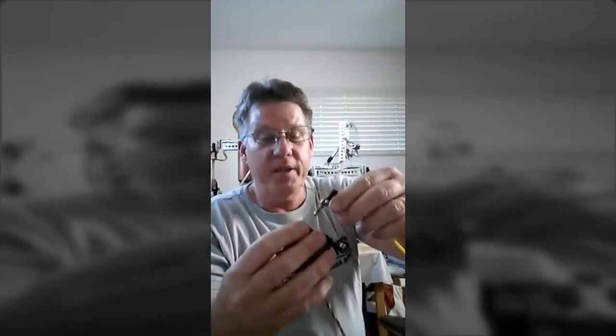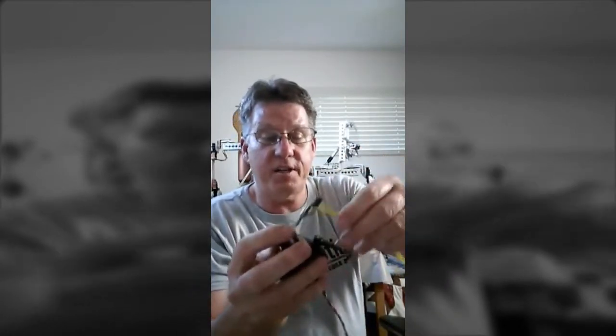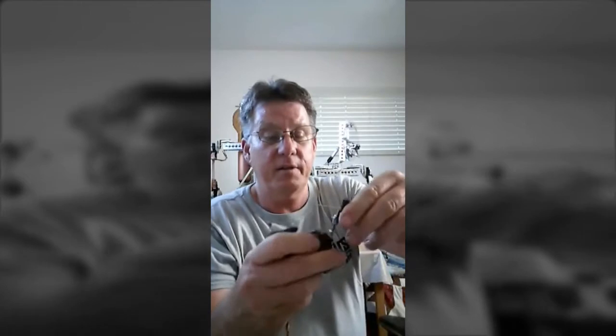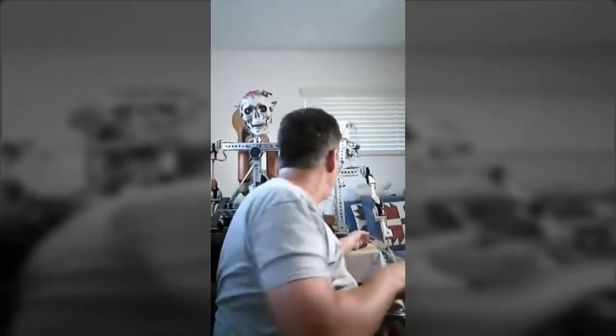And so this is how I'm going to do mine. I'm not installing the servos in the head. I'm going to be using cabling. So this fits in here. Try it the other way. It's going to fit in here. It's going to drive this cable, and my servos will be mounted outside of my head, and the cable end will go up there and drive my different motions.